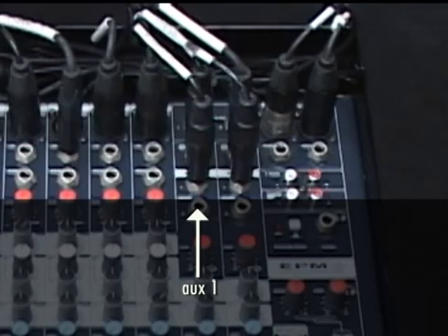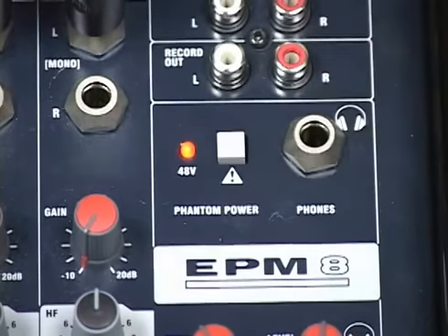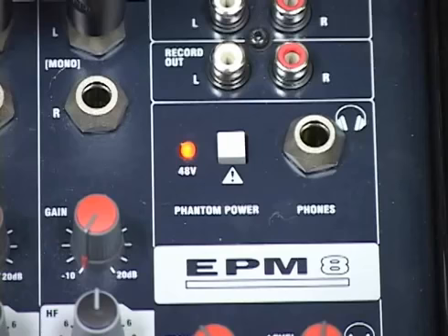Aux 1 is the output to announcer's headphones connected at the I/O panel. And finally, Aux 2 is the output used for the optional in-ear monitoring system. The phantom power button and the corresponding 48-volt LED indicator will be on. This is so the muting circuit will work properly on your announcer's interface and should not be turned off for any reason.